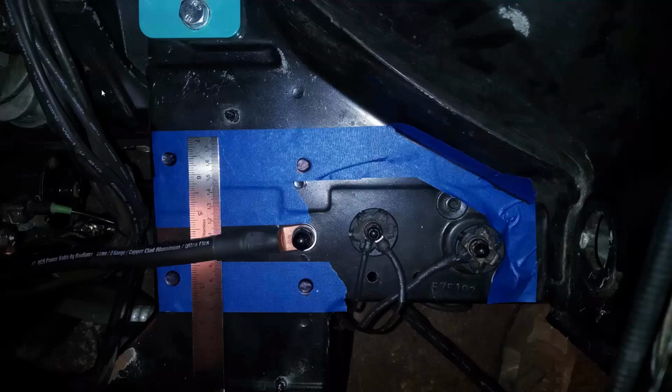And one of the things here is this is a photo. I did my best to hold the camera straight above the part and as far away as I could, but I still had issues with perspective skewing the photo here. So it's very hard to take accurate measurements with a photo. The best thing that you can do is stand as far away as possible and use a zoom lens. If you use a zoom lens, you're going to have less issues with perspective. The image is going to appear flatter. But if you have to stand close and you can only use a focal length of, say, 20 to 50, even up to 70 millimeters, you're going to have an issue with perspective.